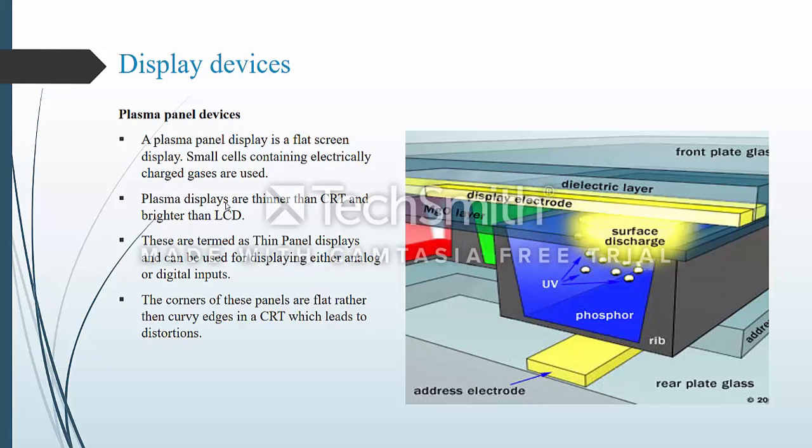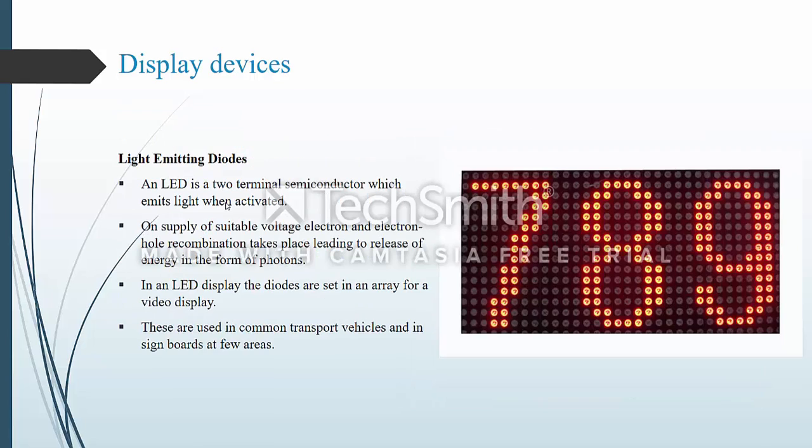Each pixel has three composite colored subpixels. When they are mixed proportionally, the correct color is obtained. There are thousands of colors depending on the brightness and contrast of each. The brightness is controlled with the pulse width modulation technique. With this technique, it controls the pulse of current that flows through all the cells at a rate of thousands of times per second. Now, we are going to see light emitting diodes.